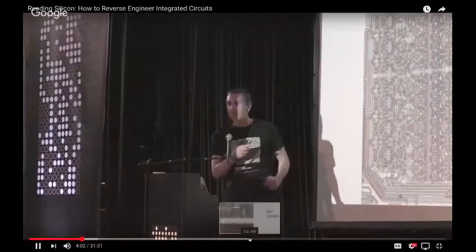Another thing is the Z80 has a couple of instructions that will swap the data in registers. And it turns out that it's actually not moving the data between registers. Instead, it swaps the control lines at the top. So it's much faster than actually moving data between registers. So that's just one of these optimizations that you find inside a chip.